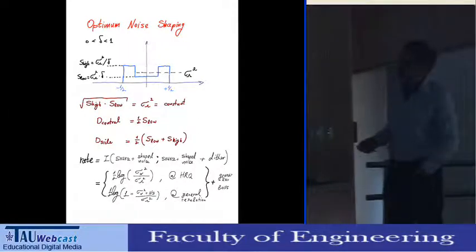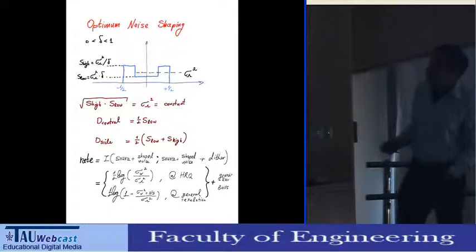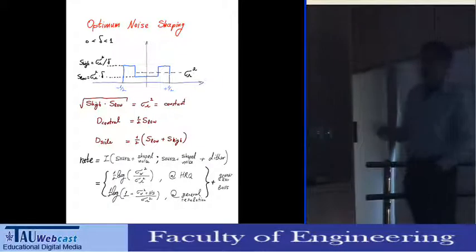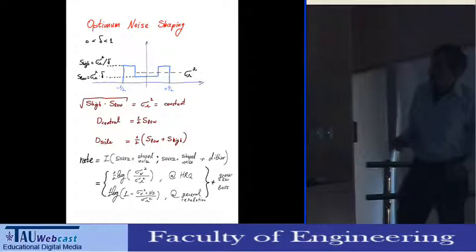And here I give you a picture of what we discovered as the optimum noise shaping for the delta sigma for multiple description. The optimum noise shaping turned out to be this two-step spectrum. So I have one step in the in-band and another, flat step at the out-of-band. And due to rules of filters, these are minimum phase filters.